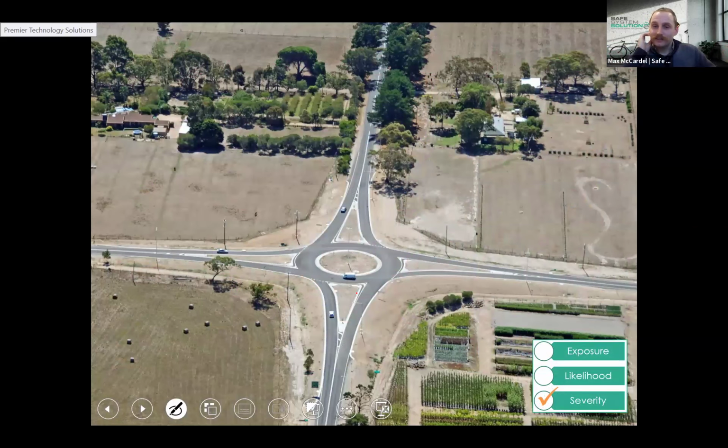Compact roundabouts. Is this one a compact? Let me have a look. No, this one is just a regular roundabout. So this one, as you can see, involves quite a lot of land acquisition. We already talked on why we like the roundabout is because if we do have a collision occurring here, the kind of angle that that collision occurs is much more favorable.